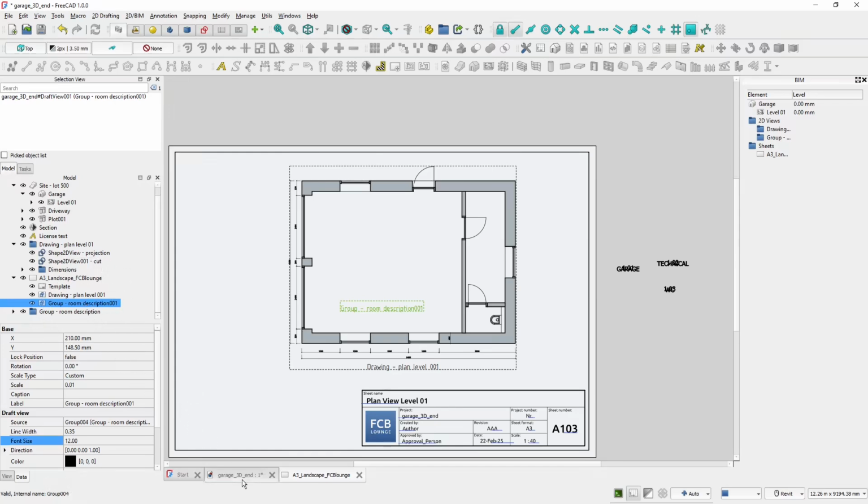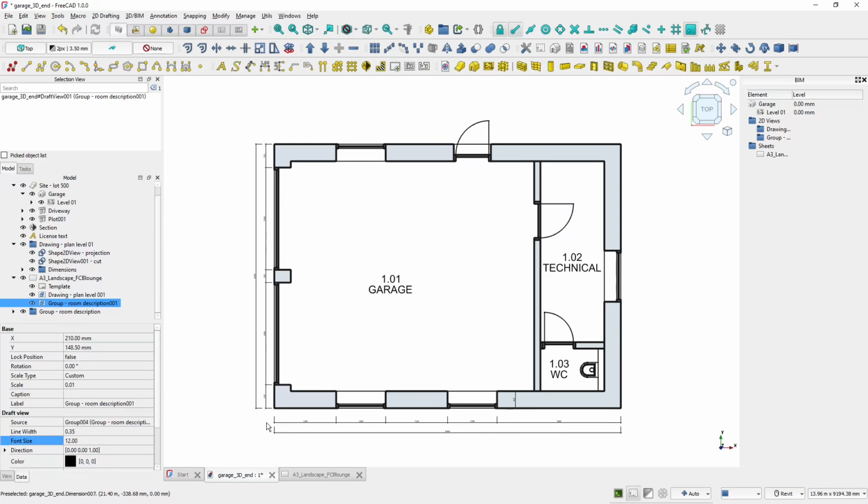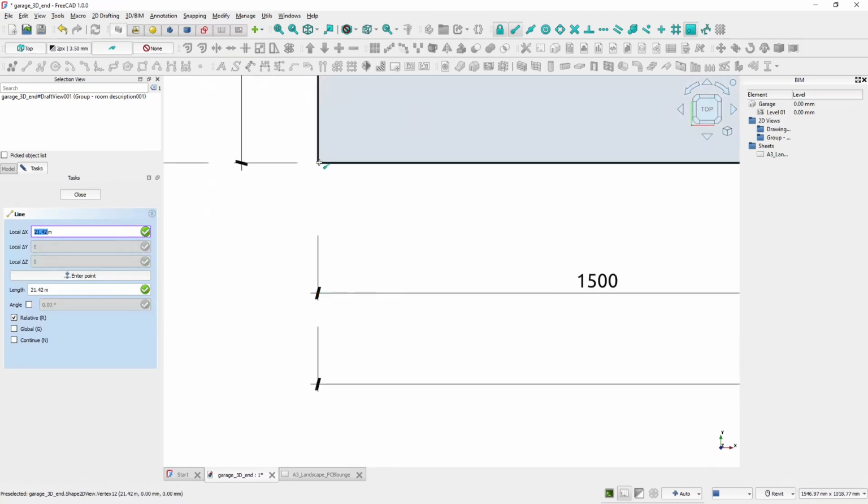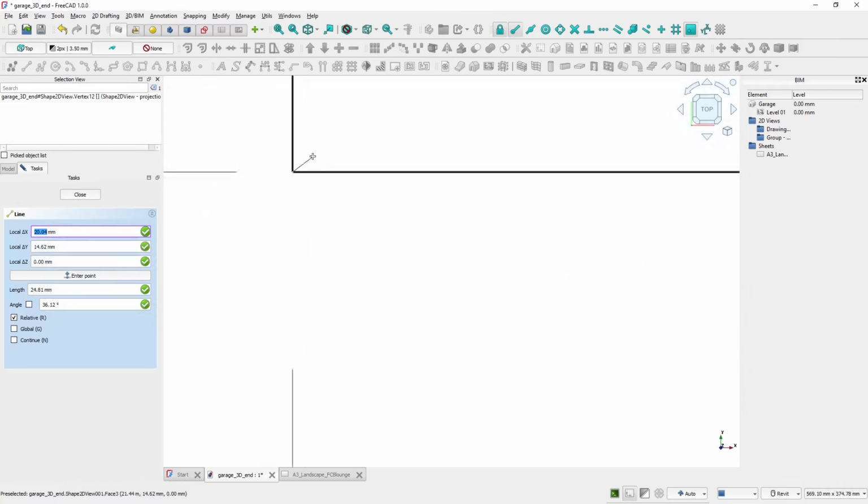So we will have to do a little thing, which is we will create a custom small object, and then the text will be placed correctly. So I will create a custom line which will be very short, but I will place the beginning in this corner, and I will make the second click. I will turn off snapping, and the second click will be here.